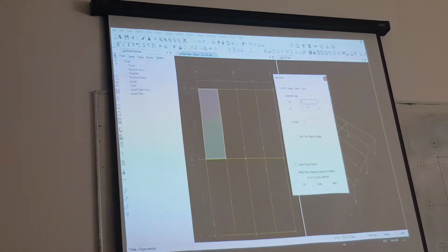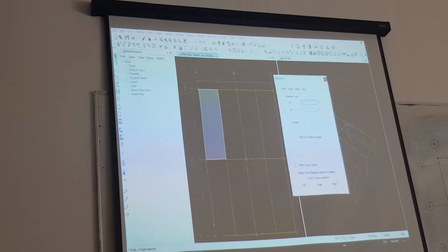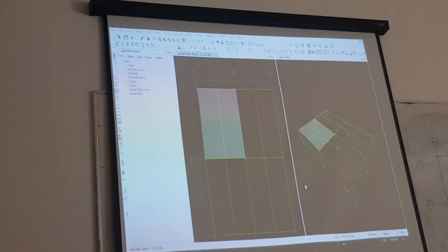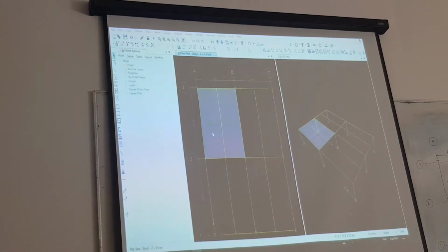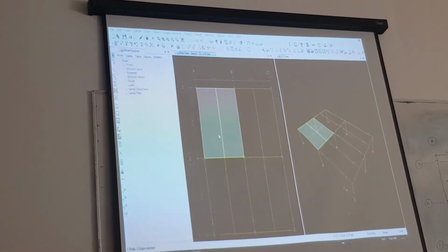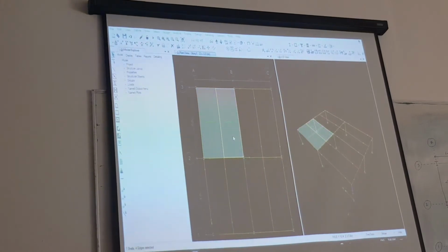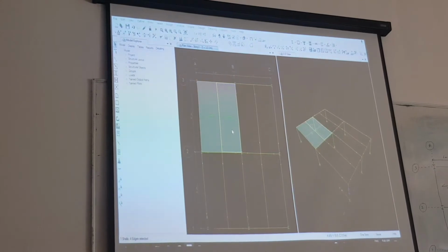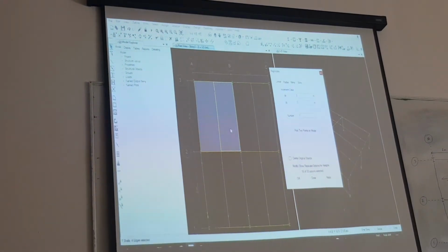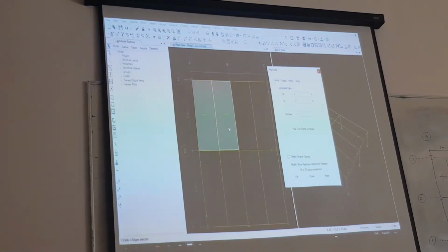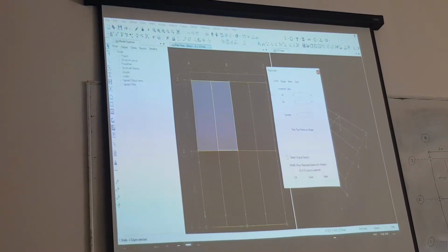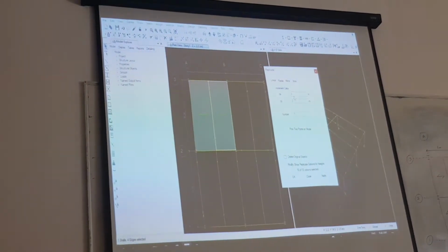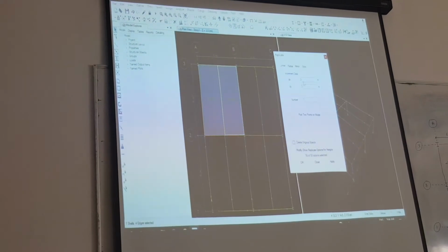Type 3 meters in your dx increment data and apply it, and it will simply draw it over there. Again, I am going to select these two. Let us not select two, it will become a bit trickier. So click on the second slab, go to replicate, or simply use the shortcut Ctrl R, and again we are going to replicate it 3 meters again.